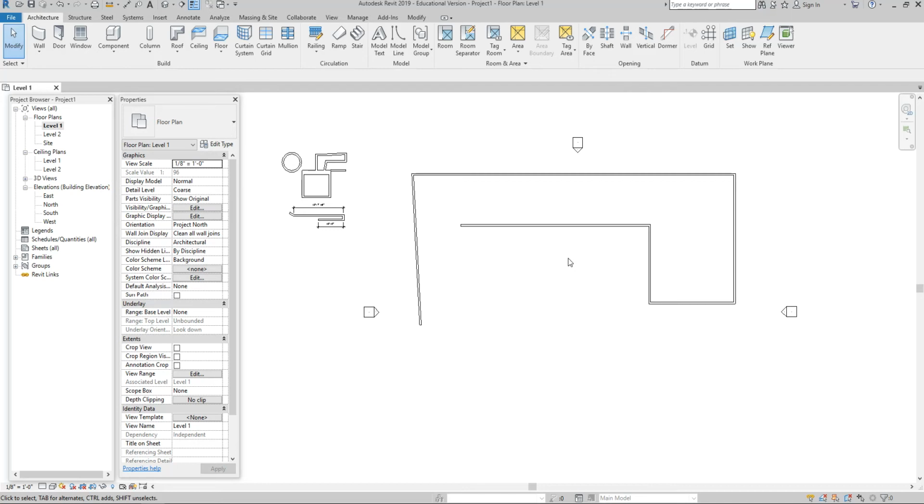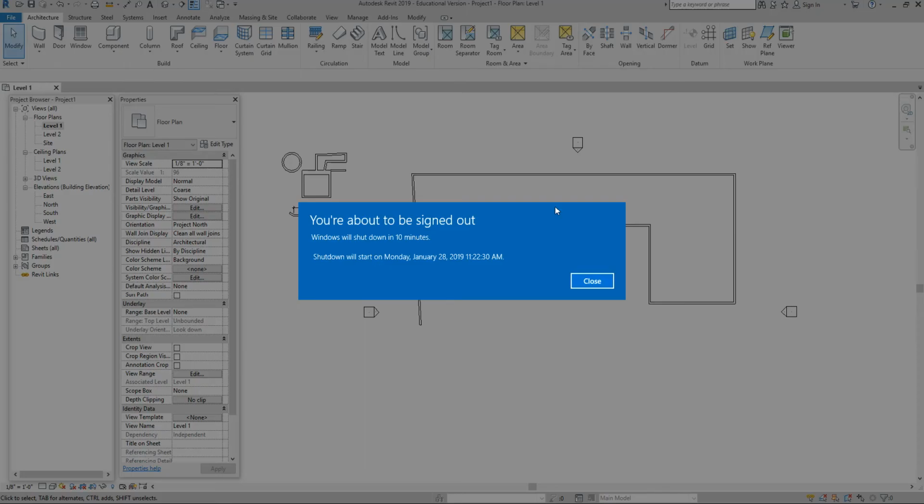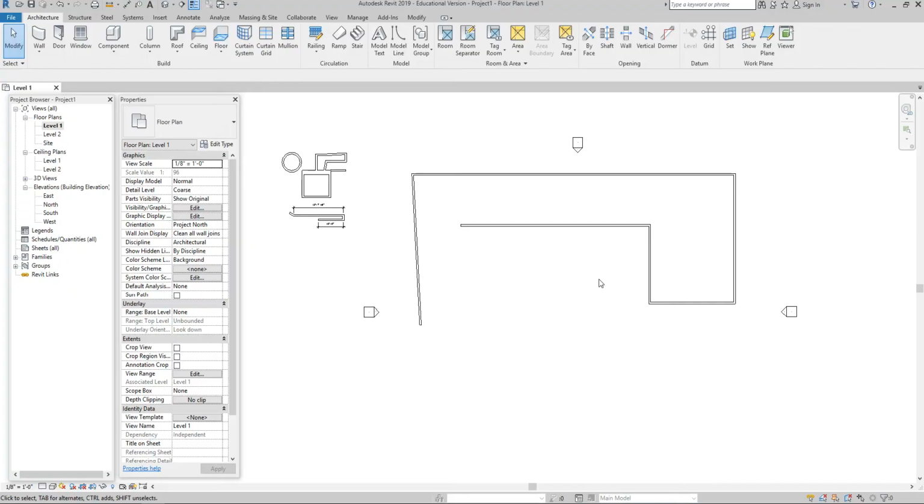So I say this a lot in AutoCAD. When you're drawing, sometimes you have to create extra geometry to draw geometry, right? Meaning sometimes I have to offset one line 10 feet to draw a perpendicular line that bisects it, and I know that length is 10 feet. And then you have to delete what you don't need. But in Revit, they've come up with a system of reference planes to help you do that without having to delete them when you're done with them. We have 10 minutes. We can get done in 10 minutes, right?